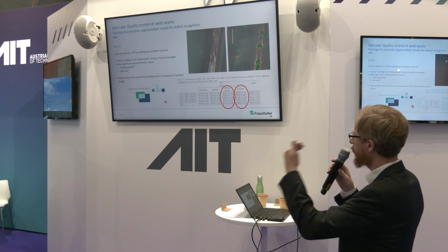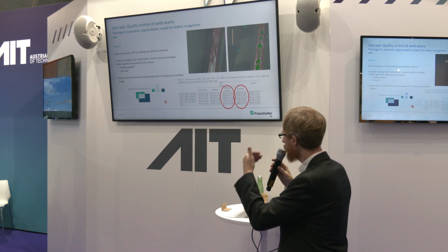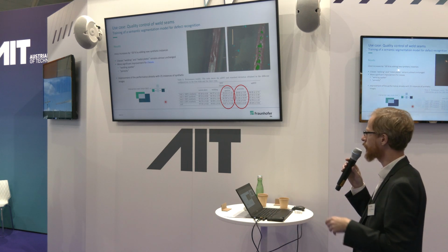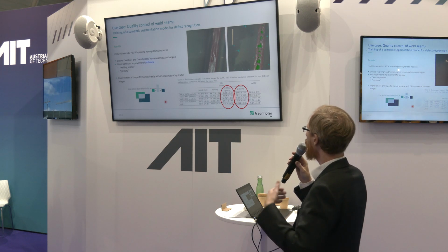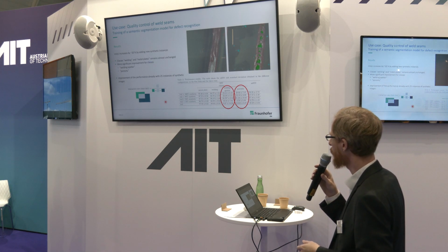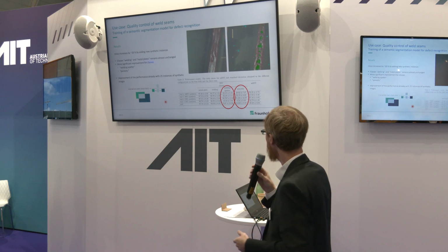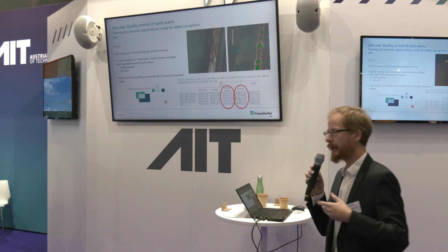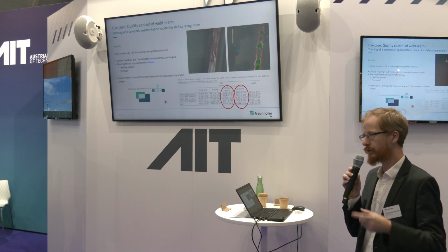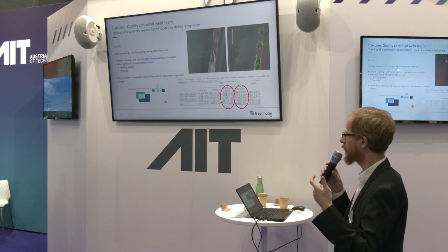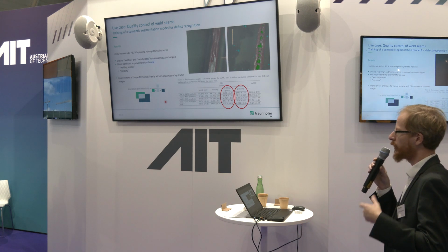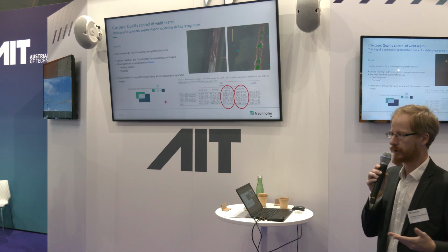But if we step by step increase the amount of synthetic data up to 100% additional synthetic data, so we have 202 real images plus 202 synthetic images, then we can increase this intersection over union to a value of 23.44 for the welding spatter, and for the porosity to 28.02, which then makes it useful. And to be honest, in most cases it will not be so relevant to localize a welding spatter at the exact position. But we now have a more or less reliable result we can use to evaluate if this welding seam is good enough or not good enough.